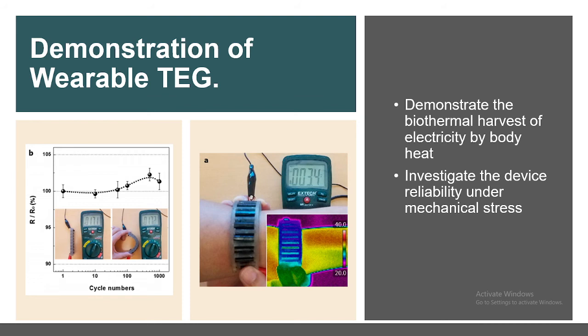When the delta T was 7 Kelvin, it is noteworthy that the voltage per unit weight of the prototype FTEG is around 170 millivolts per gram. Due to the lightweight nature of CNT sheets, only 9 grams of CNT sheets is needed for generating the same potential of 1.5 volts that standard AA batteries produce. These results show great potential for powering personal wearable electronic devices.